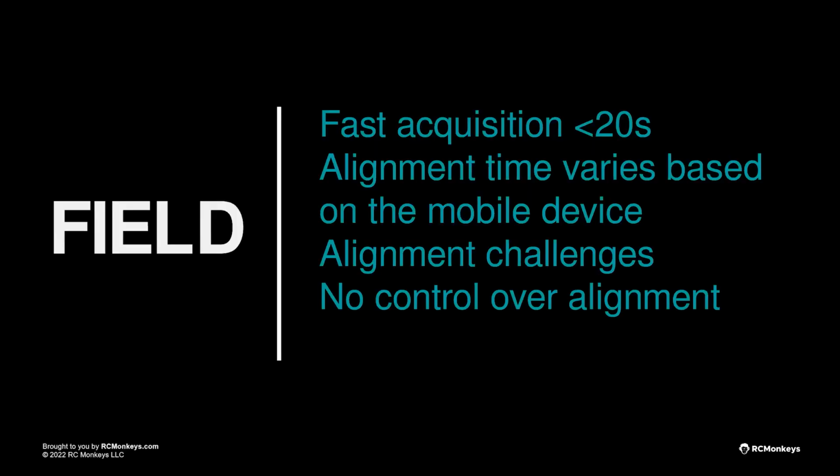All right, so the other thing, if you use Matterport, you're already used to this. There's not a lot of control over the alignment. So that's something that I would love to see in the next few updates. Especially if you tend to stop and move around the building, when you move your scanner or your camera, you're hoping that you're going to get a good alignment. Sometimes it works, sometimes it doesn't. So you kind of hope things will go well.